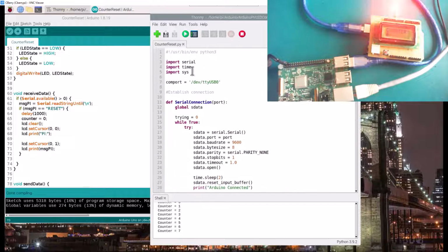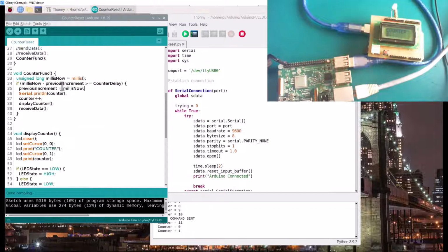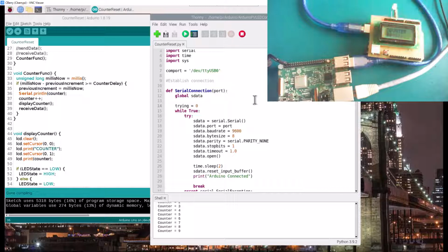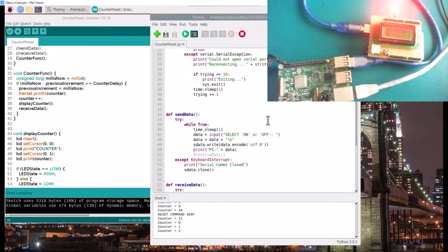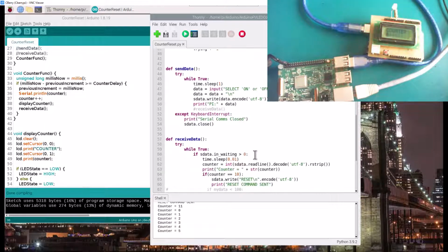Now the next method that we can try to mitigate that is to call the time function here, to import the time module on our Python script, which is already here. The Arduino is making use of the millis here to increment a counter variable. Now we can use a time now here so that we can check for ourselves a 1 second delay, and that way we can see the discrepancies between the real time that's happening inside the Arduino and the one the Raspberry Pi is going to be counting, and then see if we're still going to get the situation that we are getting here.